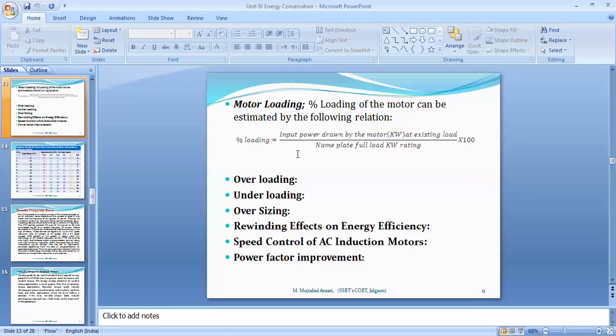The rated voltage is applied across phase to phase, so the phase voltage is the same in the case of a delta connected motor. Now, if you change it into star, what will happen? The phase voltage is going to reduce, therefore the iron losses are going to reduce, because the iron losses depend upon the rated voltage. So suppose, for example, the rated voltage is 415 volt.